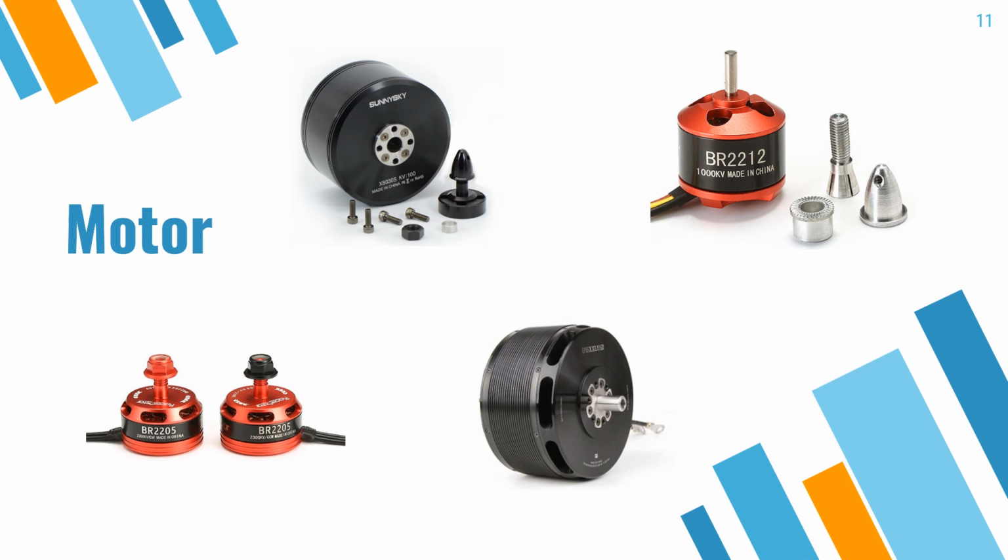Okay, let's look at some examples to clarify this up a bit. The motor in the right corner above, the BR2212, is a motor capable of producing around 1 kilogram of thrust and has a kV of 1000. This is also the one we use for the DronoBox. The one to the left of it, the Sunny Sky, the black motor, is a motor capable of producing around 20 kg of thrust, but only has a kV of 100, so that is only a tenth of the BR2212. So this means that the BR2212 has a higher end speed, but is less efficient than the Sunny Sky, so it drains more power, and is also capable of producing less thrust than the Sunny Sky.